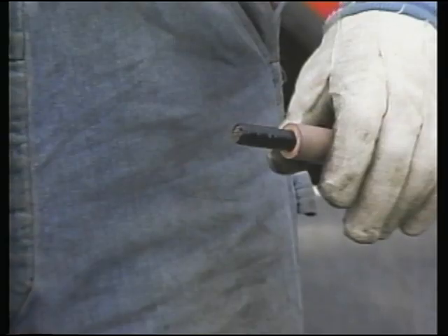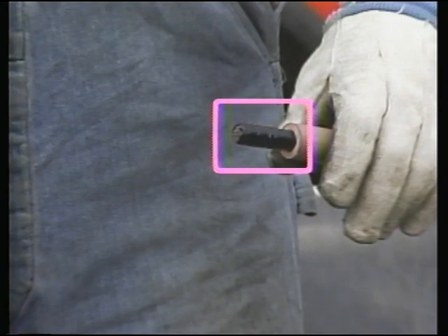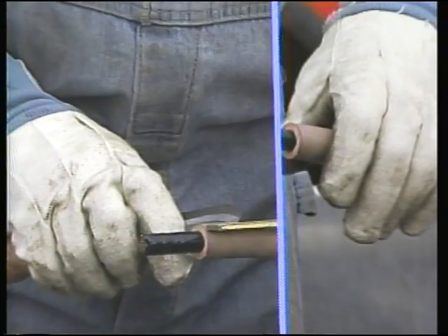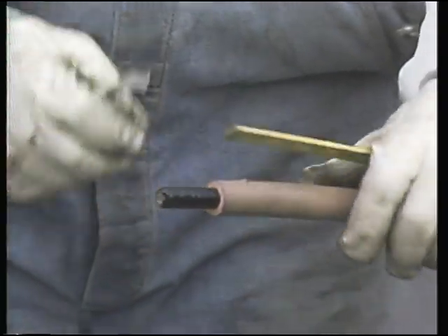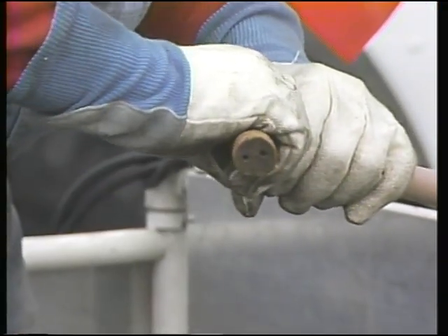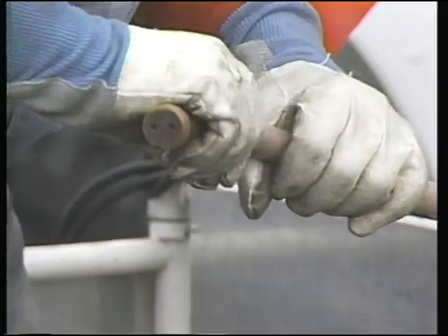The next step is penciling or tapering the insulation. To protect the conductor during the penciling process, a layer of vinyl tape is applied. Tapering the insulation provides a smooth transition between the cable insulation and the tape insulation that will be applied later. A measurement is taken to determine how far back to taper the insulation. Then, the worker tapers the insulation toward the conductor to the specified slope.